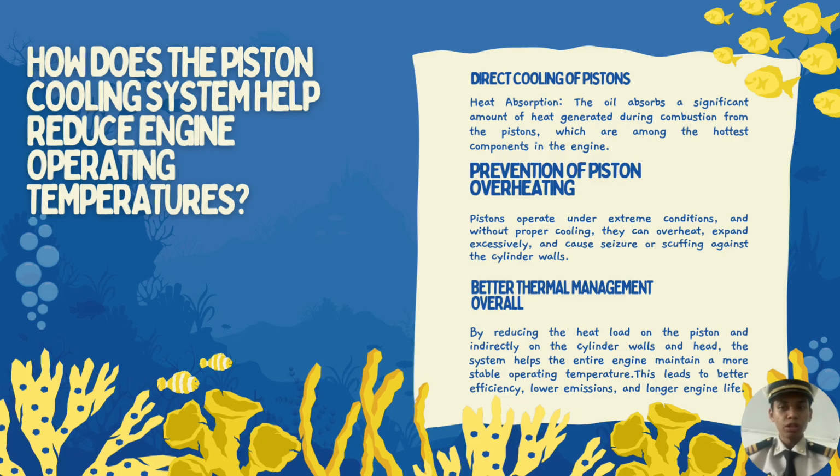Pistons operate under extreme conditions and without proper cooling, they can overheat, expand excessively, and cause seizure or scuffing against the cylinder walls. Finally, there is better thermal management overall. By reducing the heat load on the piston and indirectly on the cylinder walls and head, it helps the entire system maintain a more stable operating temperature that leads to better efficiency, lower emissions, and longer engine life.